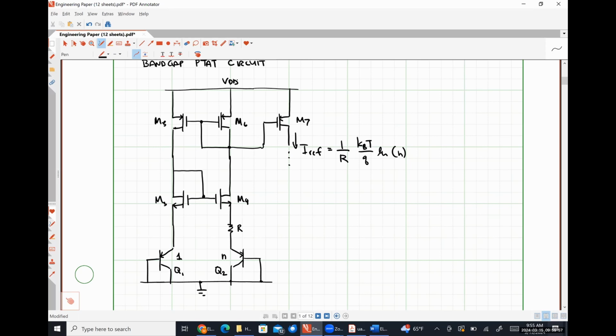So a current mirror is simply just a circuit that takes this as its input and then makes a copy of it so that you can apply this current elsewhere. And you can use current mirrors to make multiple copies. And you can also wind up scaling that reference current and all that kind of good stuff. Because let's say that you design this circuit for 10 microamps, but it turns out that you need something that's driving 20 microamps to give you a better gain. Well, you just make your current mirror scaling. So that's what we're going to be talking about for the next couple of class meetings.